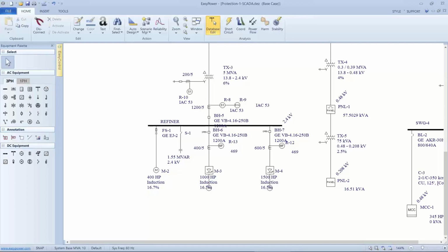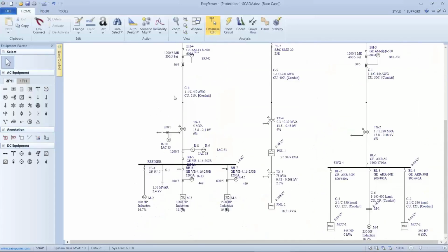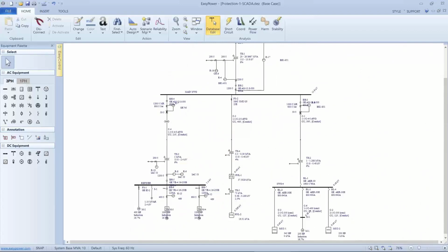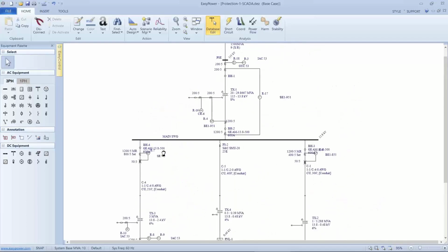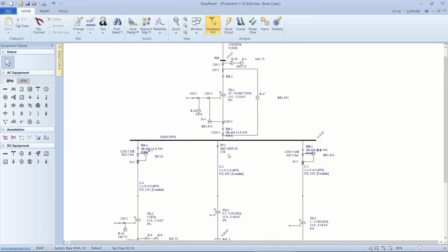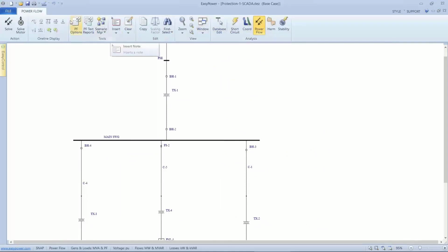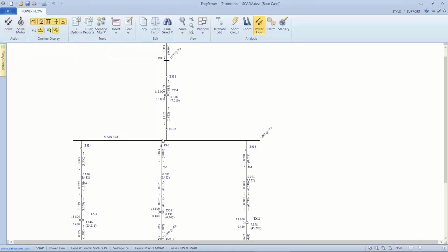Sorry about that. Now, Paul's question about the convergence being unstable. As far as I'm concerned, this is one of the most fun aspects of power flow, and it does uncover the potential for mistakes in the one line in sizing different elements. And the suggestion is, treat it like a detective story. If I go into power flow and I try to solve my equations and I get an error that says it doesn't converge, what I do is I open up all of my feeder breakers.